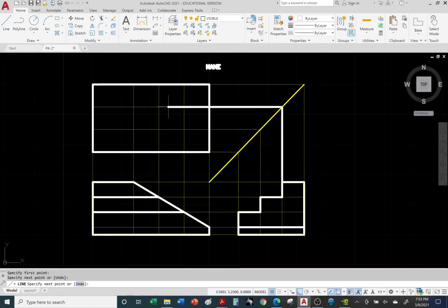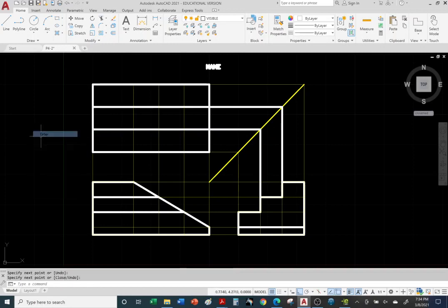Hit the 45, go across. Right click, enter. Go to the next vertex. Straight up, hit the 45 and across. And right click, enter. And we already took care of this vertex, right? It's already there. Let's delete the evidence. Delete. And we can now shorten these.